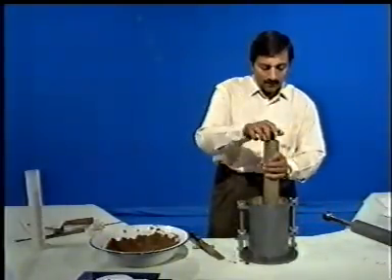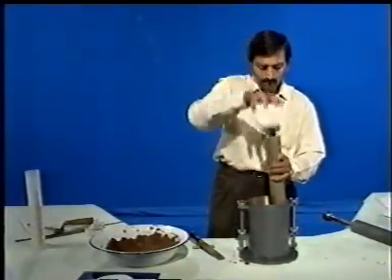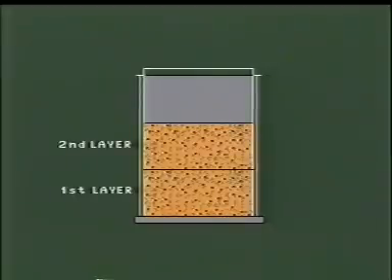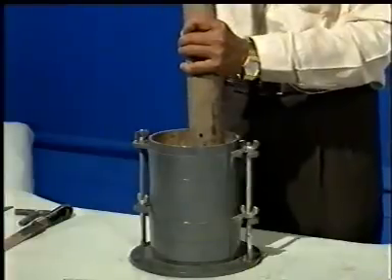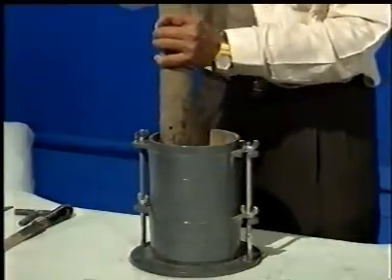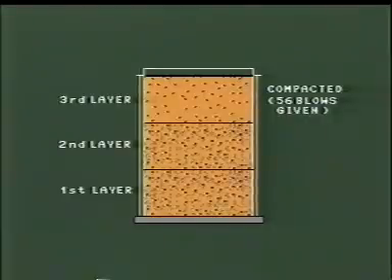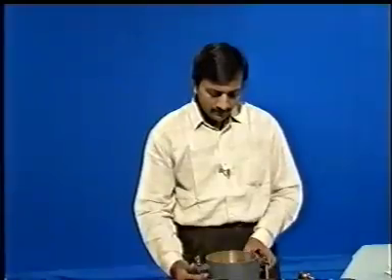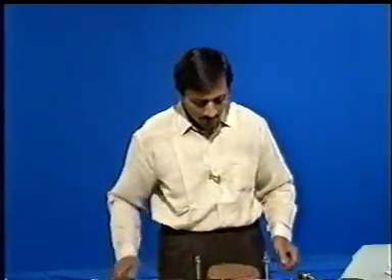Compact in the similar manner. After compacting the top layer, remove the collar and trim off the top surface.